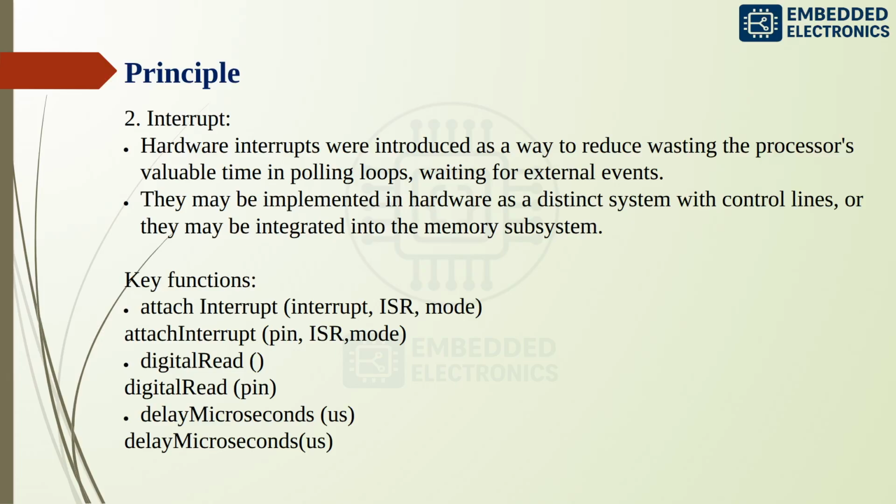And delayMicroseconds. It is used to pause the program for a very small time in microseconds. 1000 microseconds is equal to 1 millisecond. It is used for very short and precise delays. For long delays, use delay.